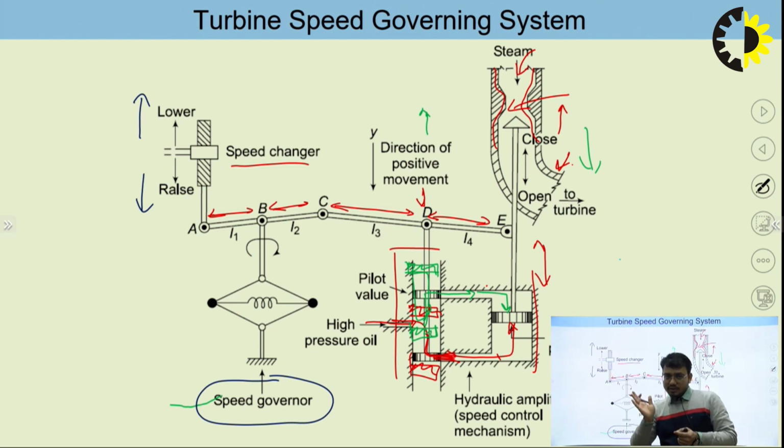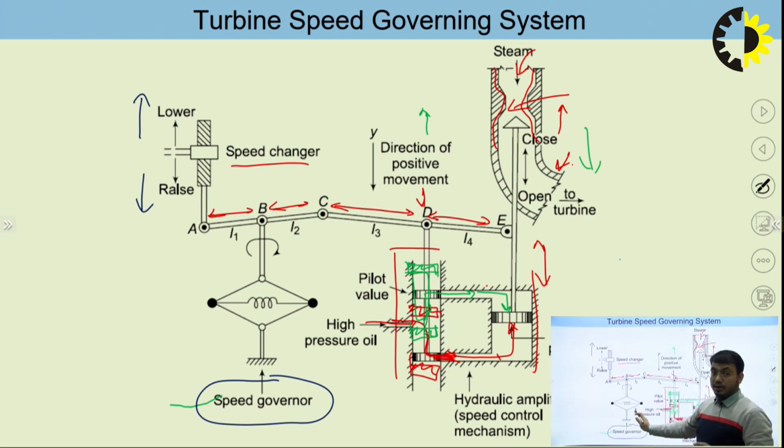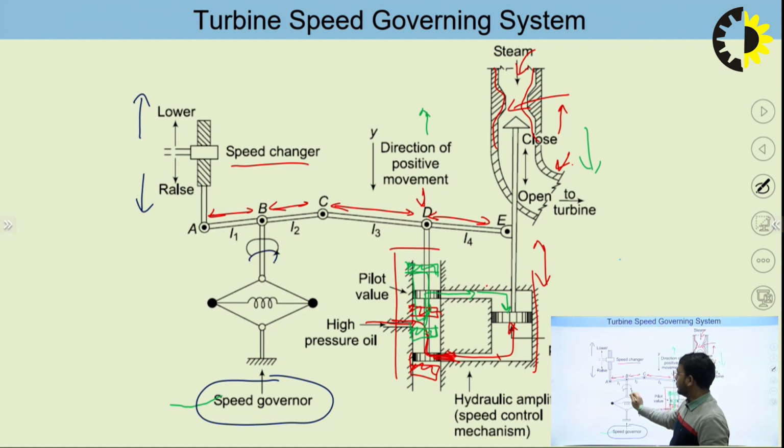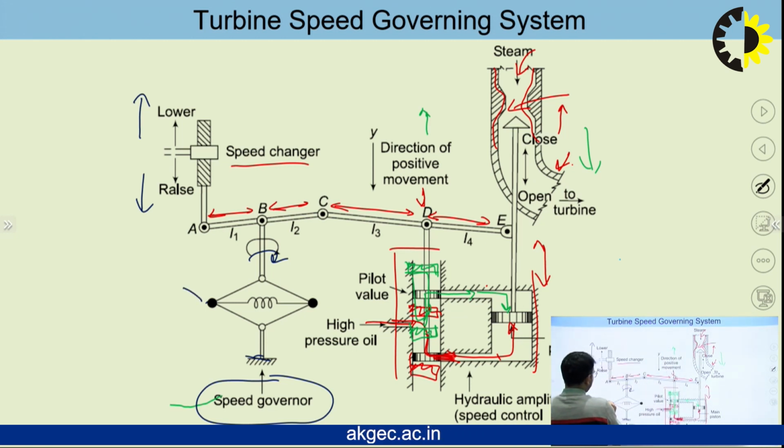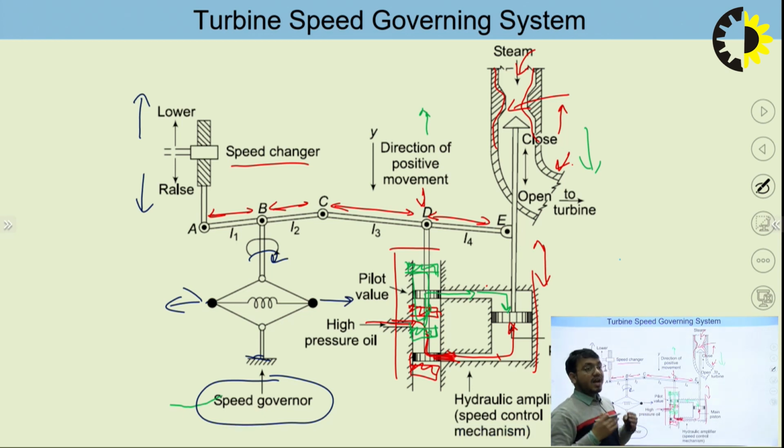Basically we can see that this is the tangential direction. So this is acting just like a pendulum over here. This portion moves in this direction, and this is fixed over here, and you can see that these are the two balls which rotate at a very high speed or lower speed. Whenever the speed is higher, these two balls move upward. Okay, so basically it does not move upward, it moves in the outward direction when it moves with the higher speed,